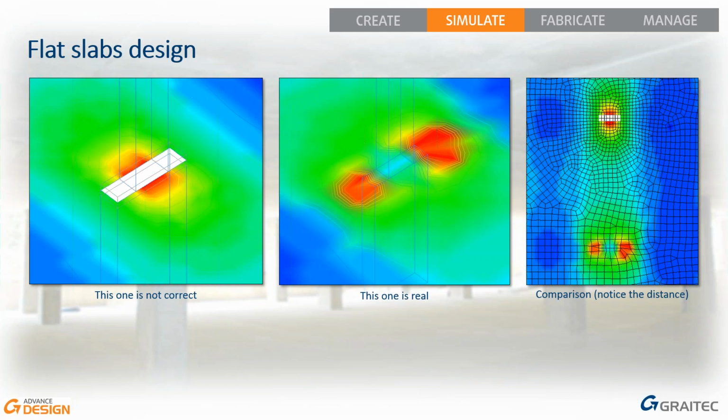So as you can see in the comparison on the right, you can see how far it stretches when it comes to the range of the bending moments. So you really need to rethink your reinforcement. So the values are nearly the same, but the shape of the design efforts is changed a lot.